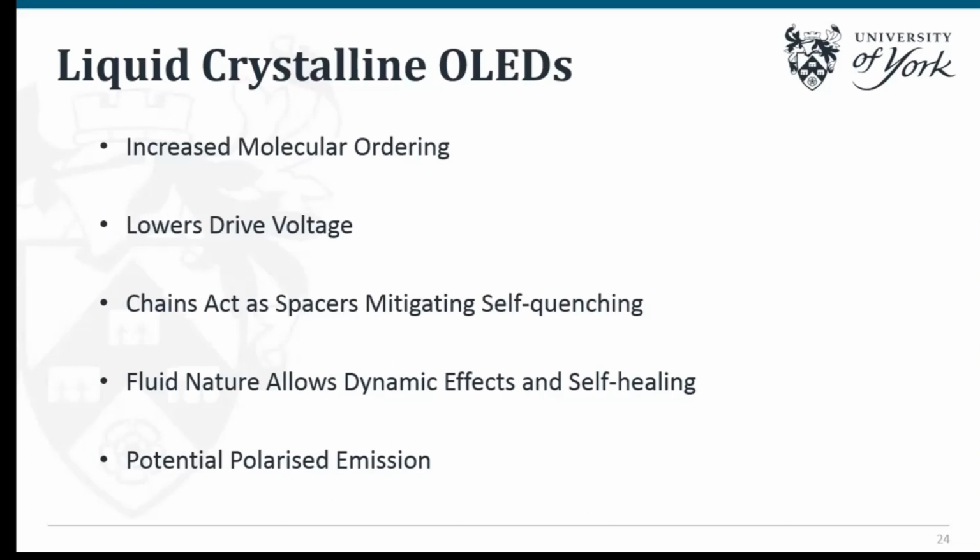The fluid nature of the liquid crystal phase can also allow dynamic effects and even self-healing sometimes. And potentially you can polarize the emission of liquid crystalline OLEDs, so you no longer need a polarizer, which increases the efficiency of the device and hence uses 50% less energy. So it is something that is a very active area of research at the minute.